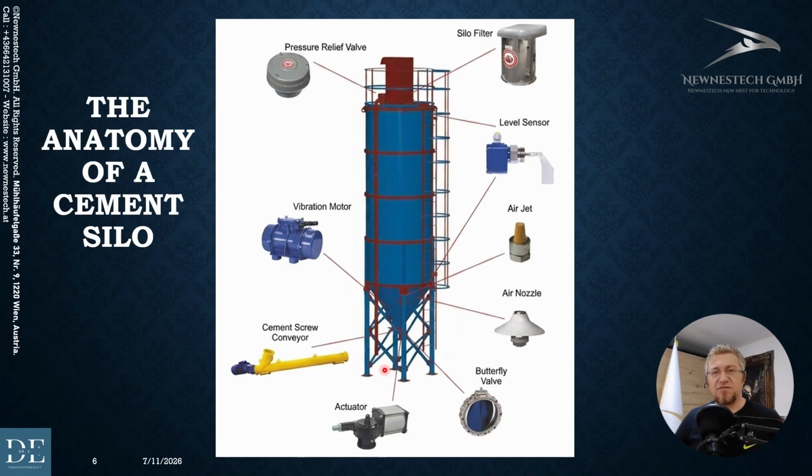For material delivery, we have a dedicated pneumatic filling pipe. The lower intake terminates close to the ground floor, allowing standard bulk cement tanker trailers to easily hook up its pneumatic feeding system. The pipe runs vertically all the way to the top roof deck. Notice that it extends half a meter vertically inside the silo. This prolonged stem ensures that the incoming cement powder is delivered flawlessly down into the center of the container, reducing wall abrasion.